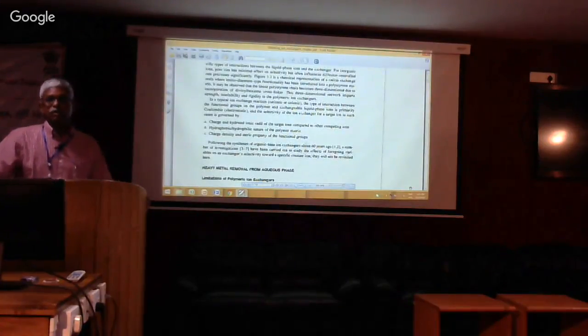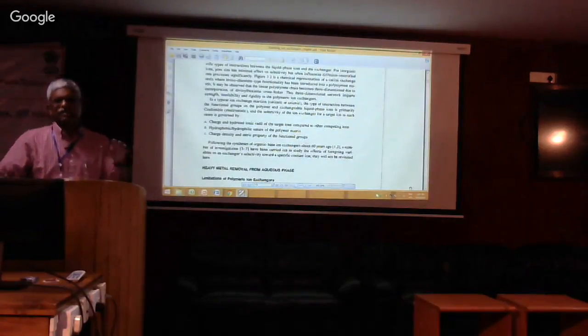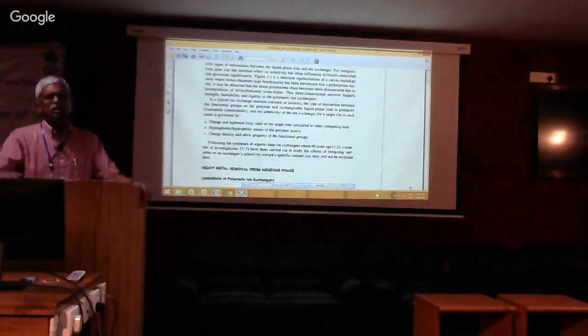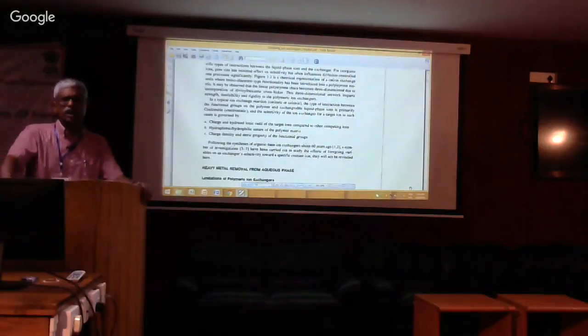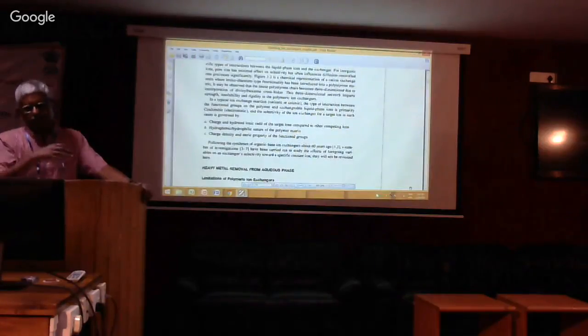What people do is they just put in an RO. And RO is kind of a kill-all technology. RO is not selective, as you know. All RO does is it just stops all these ions from going through. You just want to remove the nitrate, but now you are blocking everything.